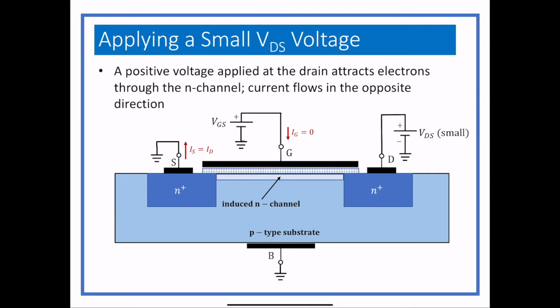And you will notice that the source current and the drain current are exactly the same current. There's no difference between them. It's just the current goes in the drain, out the source. When we get to bipolar junction transistors, that will not be the case. They will look kind of similar, but it's not the same process, so those two currents are not the same.